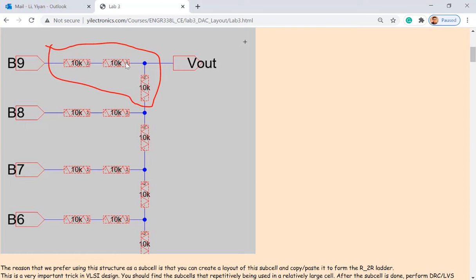If this one passes the schematic check, and you use this subcell to form a bigger cell, you get a way greater chance to pass a schematic check eventually. You know what I mean? You definitely want to start with small subcells. Super important, right? Especially in the future.